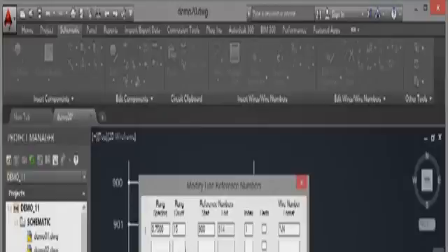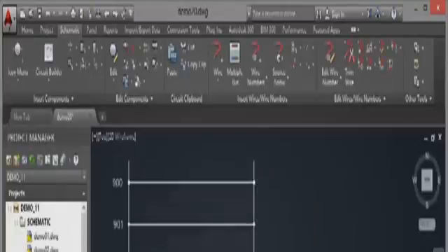If there was any other ladders in that list, over here, let's say there might be another ladder, I could then select the next line down in the numbering and it would update those numbers too. AutoCAD Electrical would pick that up though. In the dialog box, if there were any other ladder numbering sequences, it would pick them up as the next one in the list and the next one in the list and so on. In this case, there's only one, so it's the only one that I need to renumber. But that is how you renumber your ladder rungs in your ladder references in your AutoCAD Electrical drawings.